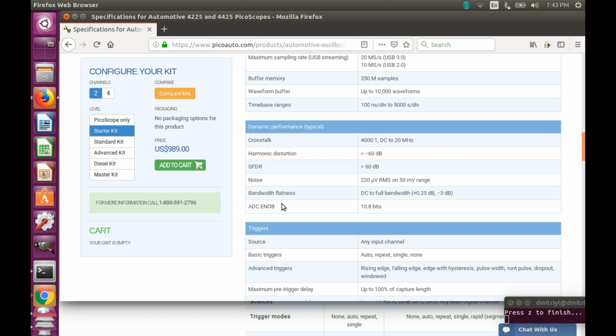Mathematicians came up with a model for an ideal analog to digital converter with n number of bits, where n doesn't even have to be integer. The usefulness of that, we can compare an ideal model to the real ADC. And the real ADC is listed as 12 bits, but it delivers the same precision as a 10.8 ideal model ADC. So this number that we have, 10.8, is approximately 1 bit less than the 12 bits, is just an acknowledgement of that.